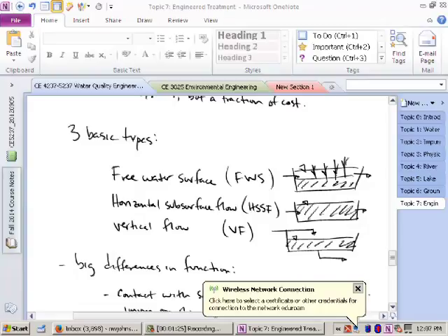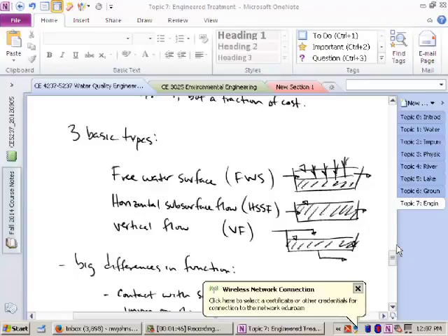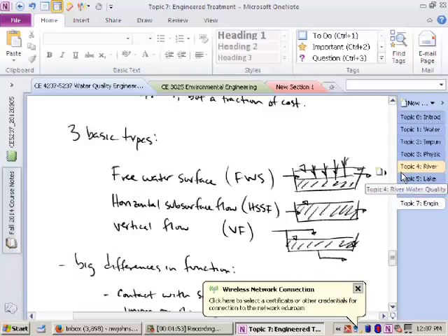It has to have the residence time to stay in the porous media in one of these horizontal subsurface flow or vertical flow, or has to stay detained in and around the vegetation in kind of a slow-moving environment in order for either the particles to settle out or some chemical reaction to happen. So yeah, free surface wetlands can accommodate more flow, but not hugely more flow, because the residence